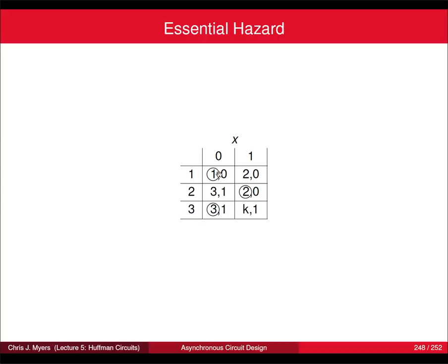And then you're going to find yourself in state 2, and maybe the logic for the output is still feeling the original 0, but it hadn't had time to stabilize. So it's going to potentially output a 1 momentarily when it's supposed to actually output a 0, because it gets excited to output a 1 because that's raced in.